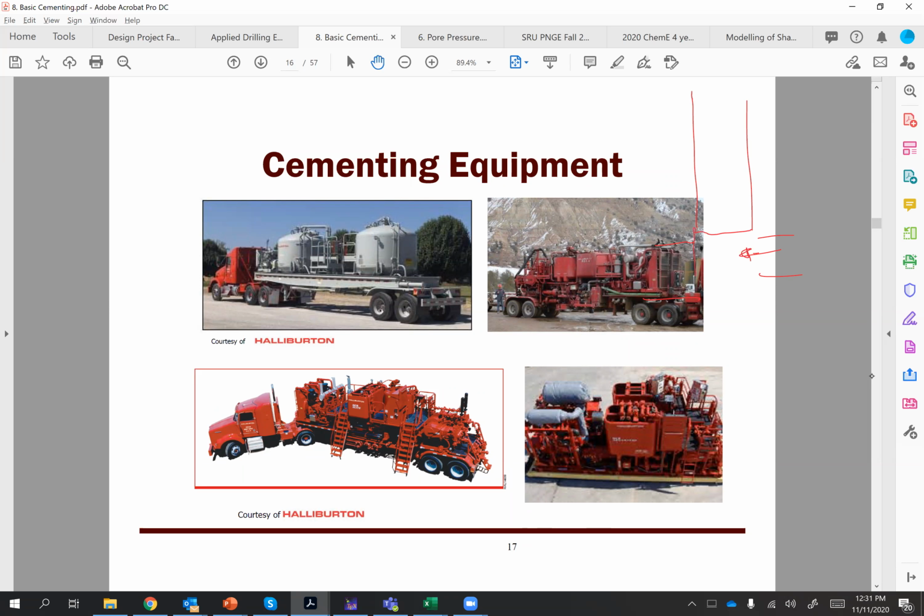You basically do a plug cementing, where you put a plug of cement at the bottom, and that way you abandon this wellbore, right? Or maybe this formation. You might have some other formations that are still producing. So you can basically have this cement plug preventing the flow of this formation. Okay, so that's called cement plugging. The process that I described was related to the cementing of casing.